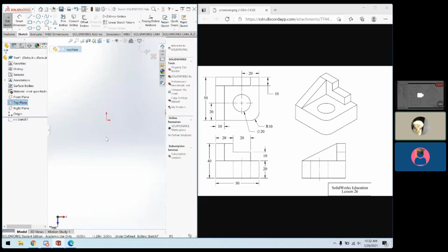Another way: say for example it was not normal, you moved the mouse or something like that by accident, and you want to go back. What you can do is over here you're going to see a negative sign sketch, and this is your current sketch, the one that is under the solid line. This is the sketch that you're currently working on.